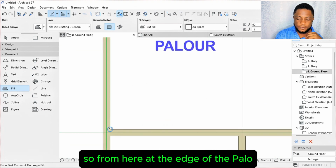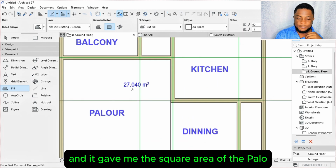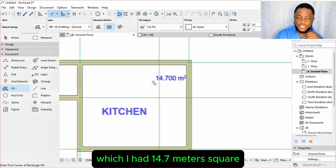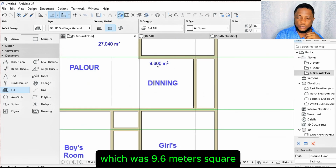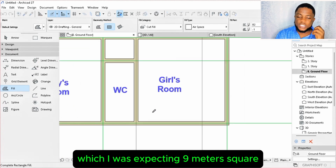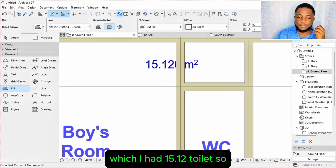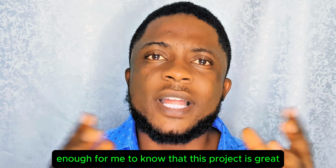So from here at the edge of the parlor, I clicked this way and I pressed enter, and it gave me the square area of the parlor, which is 27.040 meters square. I did the same for the kitchen, which I had 14.7 meters square. I did the same for the dining, which was 9.6 meters square, very big. I did the same for the room, which I was expecting 9 meters square, and I had 17.64 for boys room, which I had 15.12 toilet. So these dimensions were good enough for me to know that this project is great.